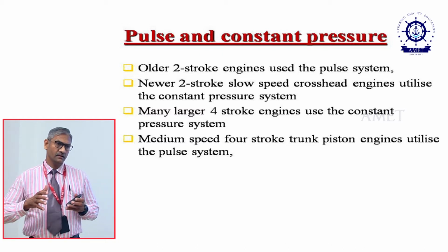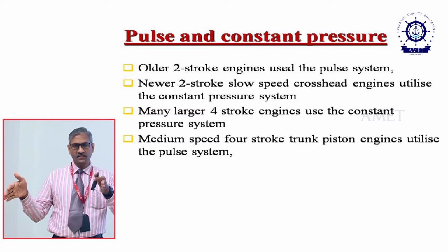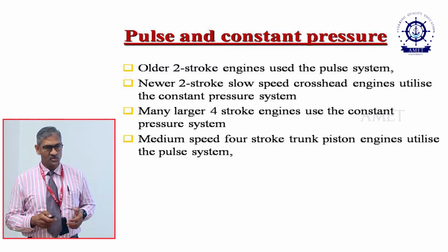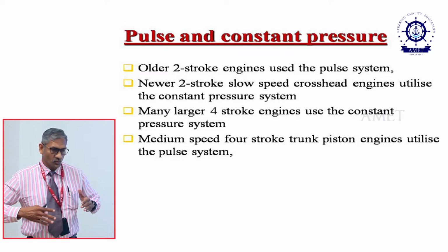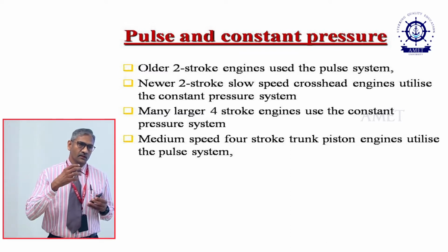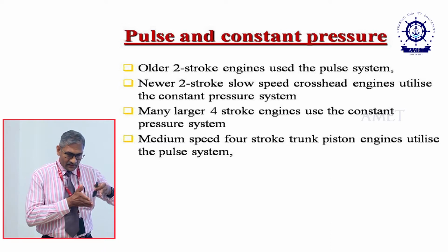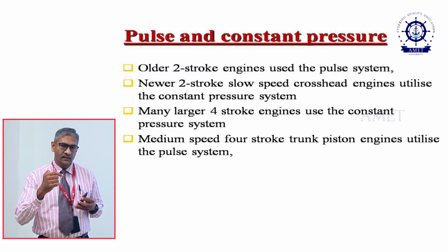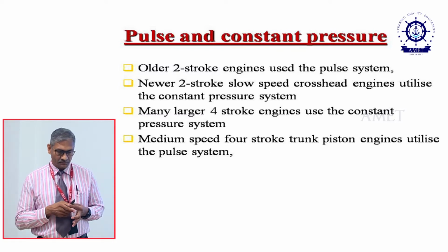Now, let us look first at the exhaust side, and then we will talk about what is called the blower side. So, the exhaust side: when you have the exhaust coming out of the cylinder, you next need to make it in such a way that the exhaust goes as you desire and rotates the turbine wheel in such a manner that it is able to generate the amount of rotation which is required by the blower.